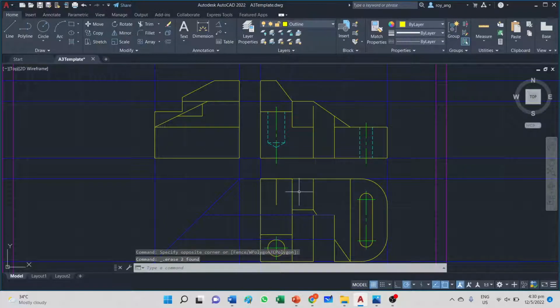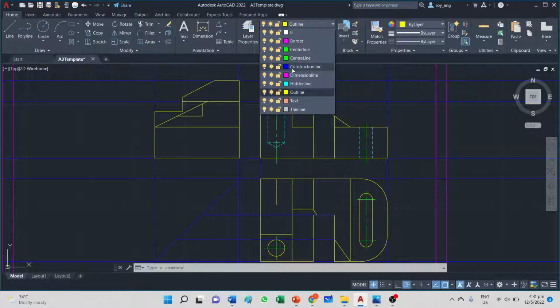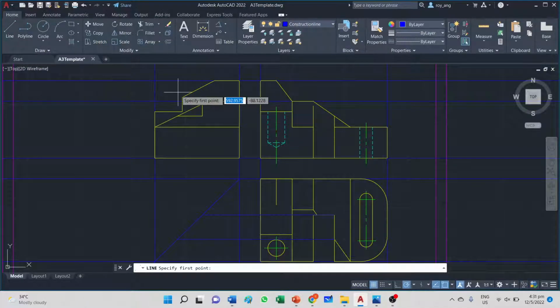Then after you've done this, you want to revisit your front view and find the missing lines that you couldn't complete in the first place. One of those missing lines is this intersection, and we only managed to get this because we can project the angle of the 28 degrees all the way to the corner.